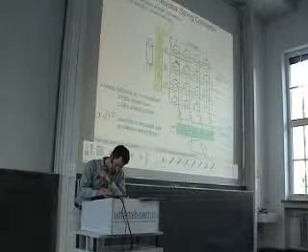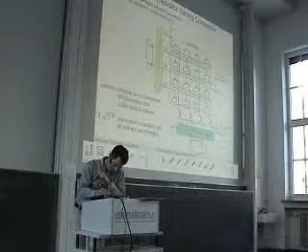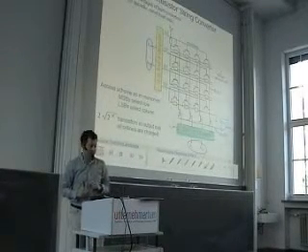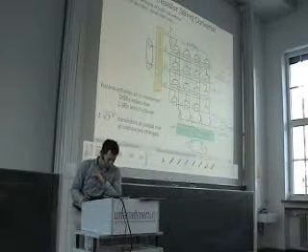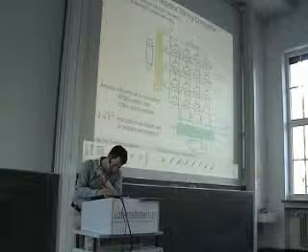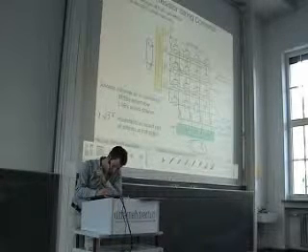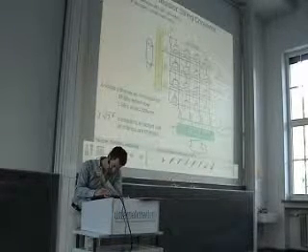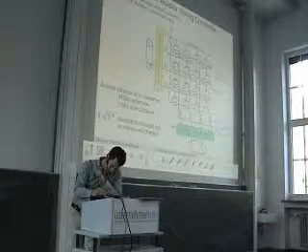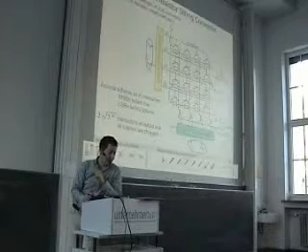And by enabling this row, we turn on all these transistors. So by turning on all these transistors, we connect the respective voltage here and here and here to this column.